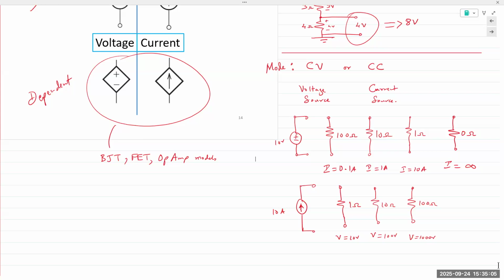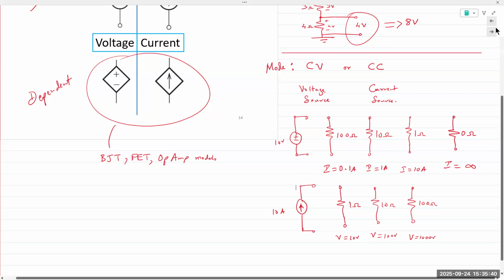That's what happens. And so when you're working in the lab, any lab, the most important thing you can do right before you begin is to set the current limit. Always set the current limit. Otherwise, you're going to end up blowing out the power supply and your circuit. Your circuit is fine, less than $10, doesn't really matter. But if you blow up the power supply, that's a few $1,000s. So we always want to set the current limit for power supplies. Doesn't matter whether you're a student or a working professional engineer, this is something you should keep in mind.